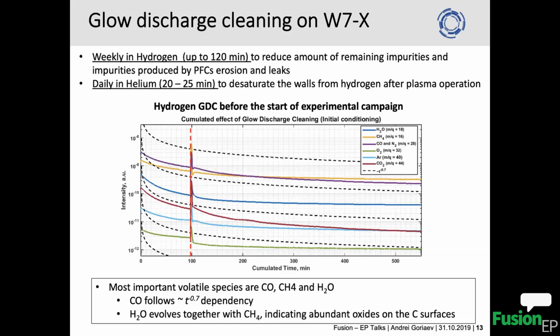Yeah, but there's a lot of things. Well, from what I learned from my short experience in the master's thesis, the RGA itself typically is calibrated against nitrogen, and then there are some relative coefficients that are built in with the device. But then there's a lot of things that can, in the end, make your measured value not so representative of what's actually going on in your chamber, depending on how you connect the mass flow controller, the pumping, or what the characteristics of your wall are, and how particles are sticking along the walls along the way.